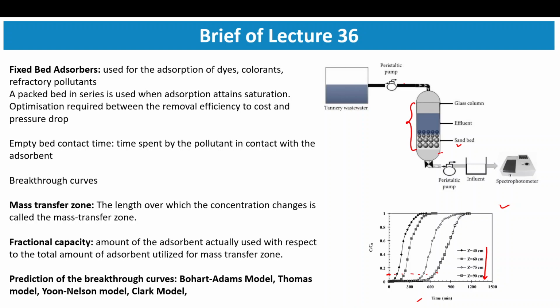What is not removed by sedimentation, activated sludge or biological processes includes a few non-biodegradable organics, heavy metals, dyes, some other colorants, refractory compounds, and sometimes oil and grease. All these pollutants we can remove using adsorption.